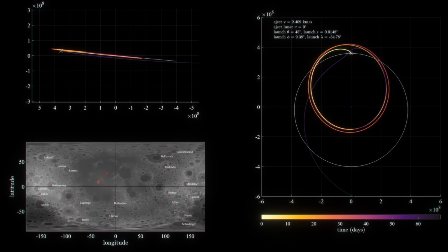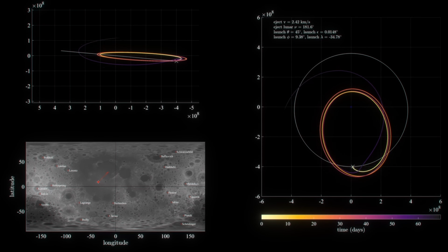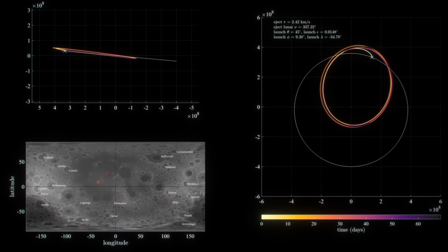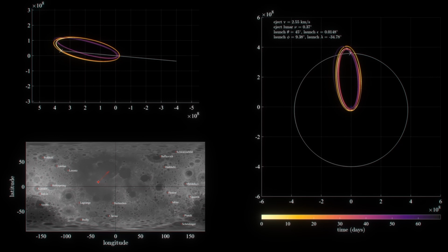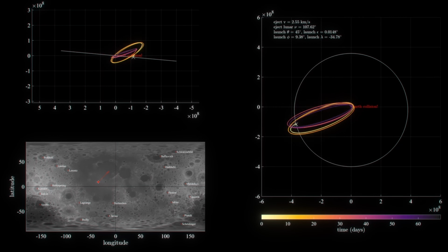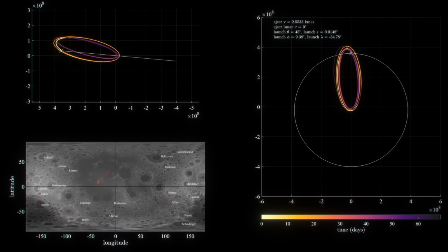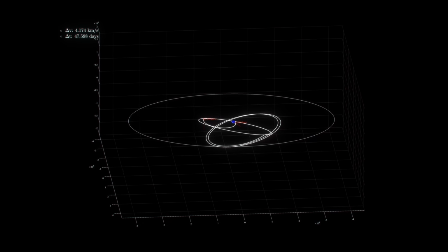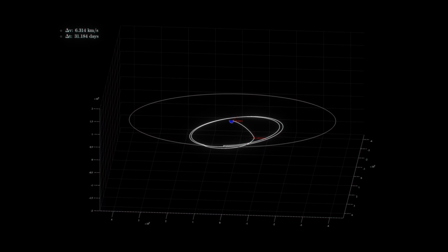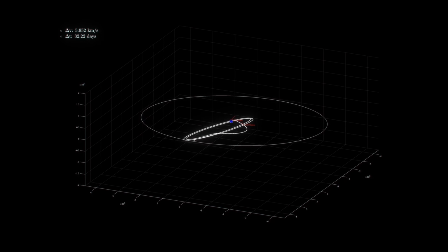And with that, we finally have all the pieces in place to run the main optimization we've been building up to. The good news is that because we invested so much time into setting up a good problem set, given all this context, the results themselves are much faster to explain. One reason the optimization took so long, other than our very poor programming skills, was the delta V cap. The allocation phase suggested that 4 kilometers per second was a reasonable upper limit, so we imposed that as a hard constraint and made the optimizer search only for trajectories that stayed below it.